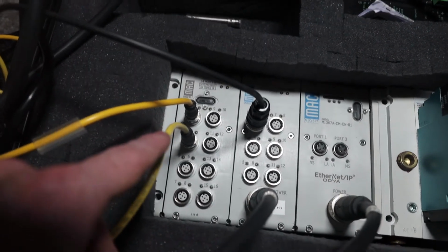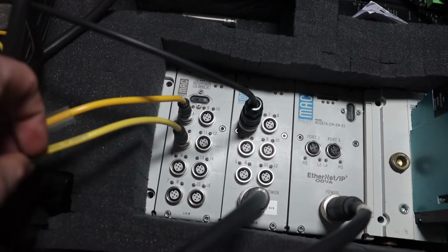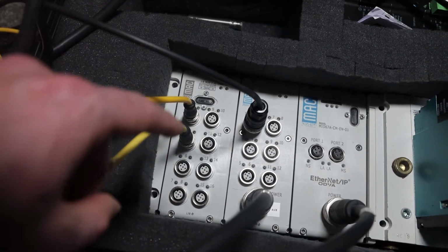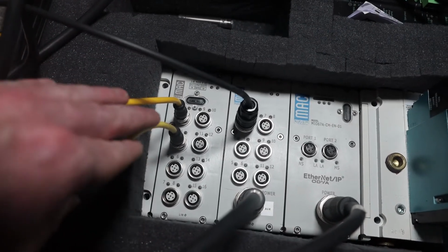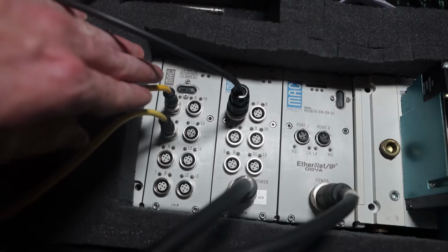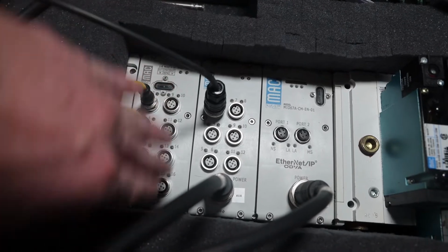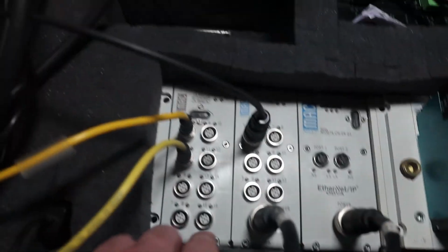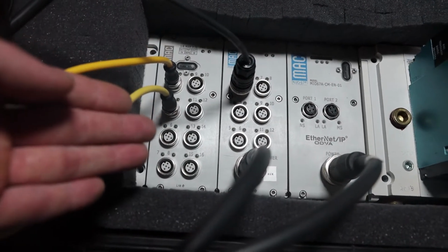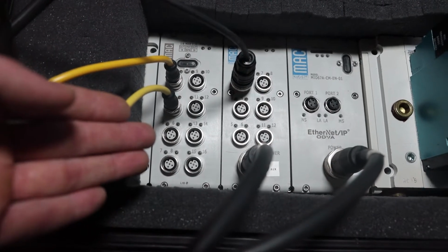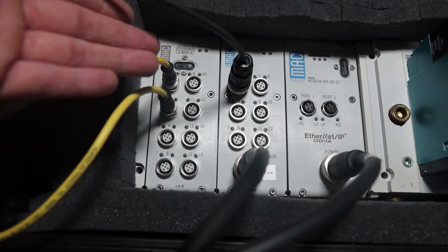And then there is the configurable IOs, which will just be your digital IO. And there's 4 different versions, I believe, of this configurable IO in the configuration settings. Basically, all that is whether you have the first 8 as inputs, and the second 8. So we have a total of 16. With the 4 different configurations, it's basically whether the first 8 are going to be input or output, whether the second 8 are going to be input or output, and then whether this device is set up as PNP